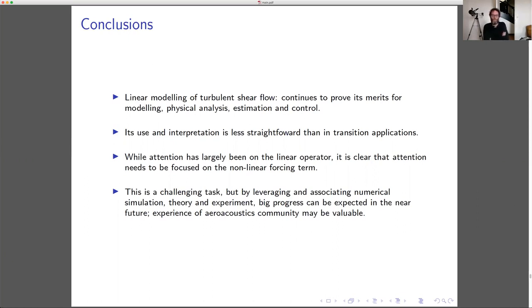One that's probably worth mentioning is the CSD, the cross-spectral density of the forcing statistics. You're talking about two-point, fourth-order statistics, so it's very difficult to converge this thing. We're talking about running large eddy simulations for 2000 convective time units, which is much bigger than what most people would usually do. And even with those lengths and the size of those databases, it's not a trivial thing to converge these statistics.